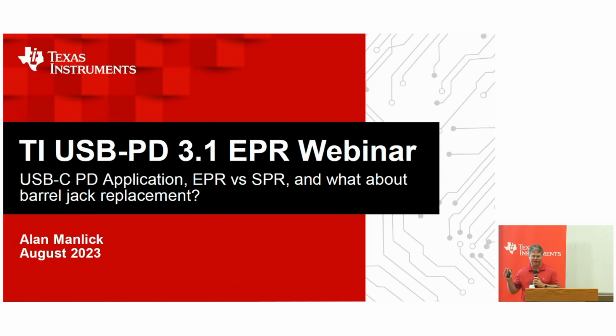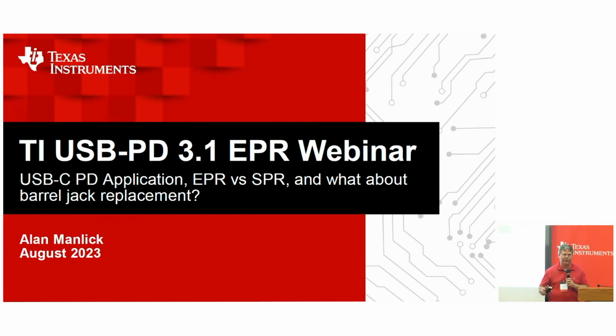Just a quick show of hands. How many people here are familiar with USB Type-C or PD specifically? The TI people. Okay. So I kept this fairly high level, fairly generic, providing a little bit of background on what USB Type-C is and how it works, to give you an idea of applications where it can fit, and then the new power delivery standards that take it up to even higher wattages, up to 240 watts delivered to applications.